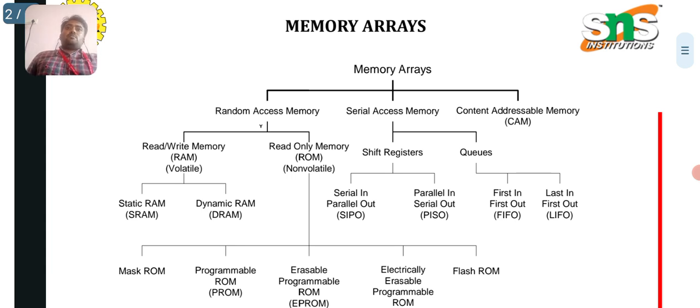Some of the key strategies for low power memory design are low power SRAM design techniques, low power DRAM design techniques, low power non-volatile memory, asynchronous memory design, reduced bitline swing, memory compression techniques, sense amplifier optimization, and standby power reduction.